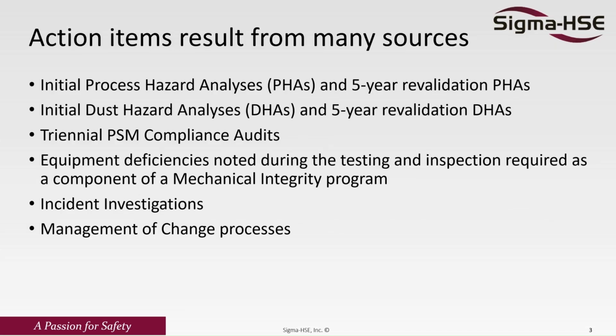So action items are an important part of your PSM program. They come from many different sources, but it's also one of the areas where it's easiest to lose track of where we are with them. Have they been completed? Are we keeping up with that? Have due dates slipped? You want to look at your sources. You have your PHAs, both initial and your revalidations. Same for dust hazards.